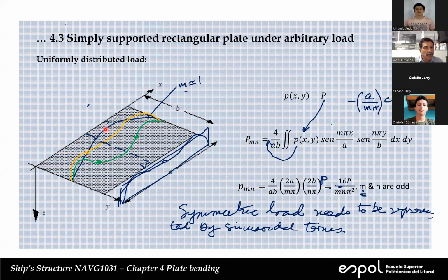Similarly, for m equal to 1, this is equal to that. So this is a symmetric function. People, be careful, because if you have a symmetric load, the resulting sinusoidal terms need to be also symmetric. It makes no sense to try to represent a symmetric load with asymmetric sinusoidal terms.